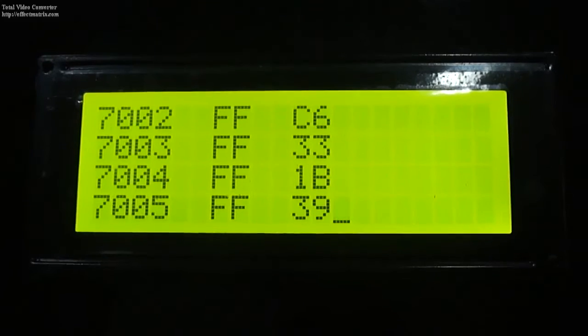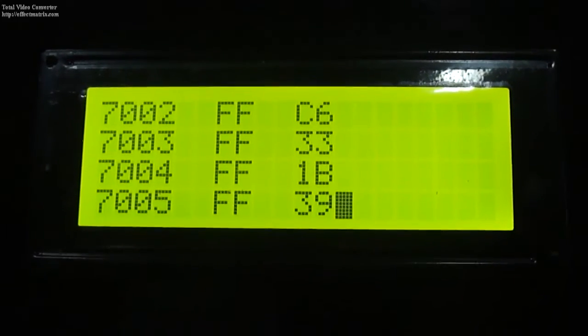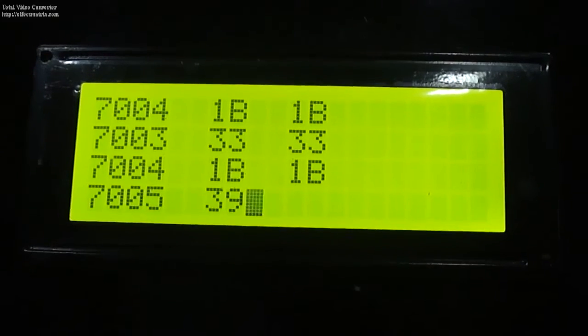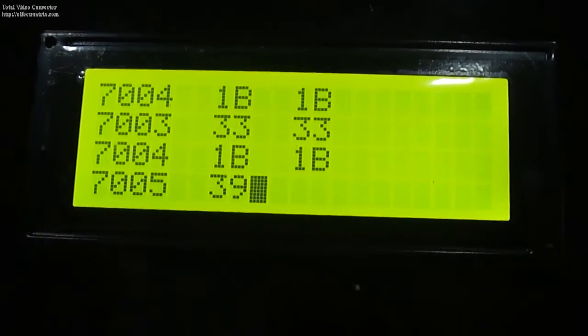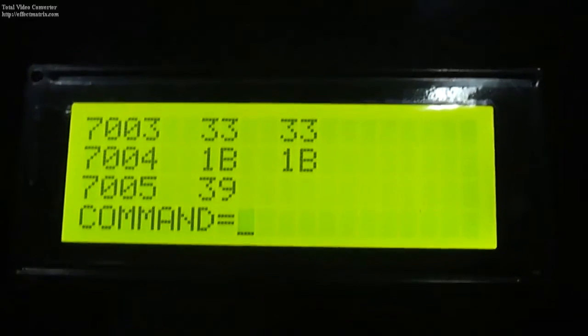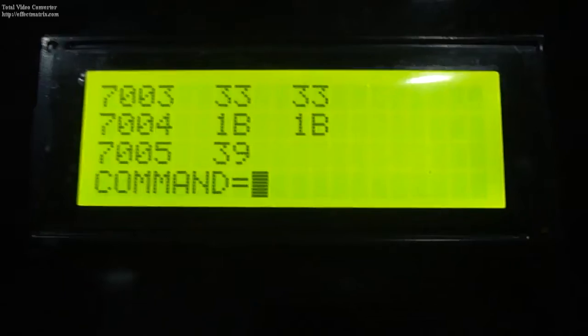1B. After completing the program, if there is any mistake in an opcode in a previous location, how do you go back? You have to press Ctrl U. By pressing Ctrl U, you go to the previous location and make the corrections. After completing the program, press escape. All this procedure we have followed manually. Press escape and it shows the command mode.